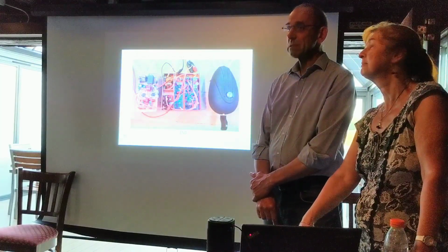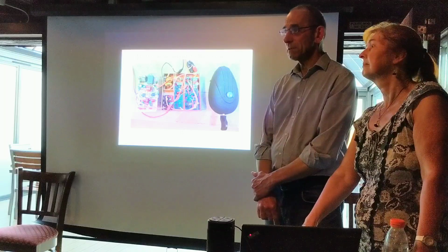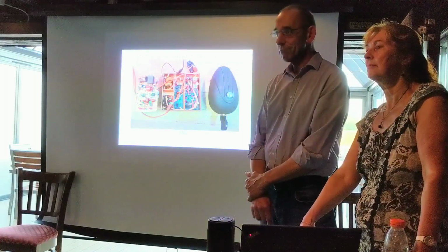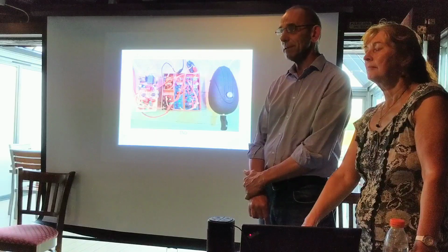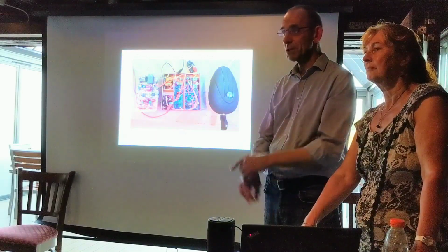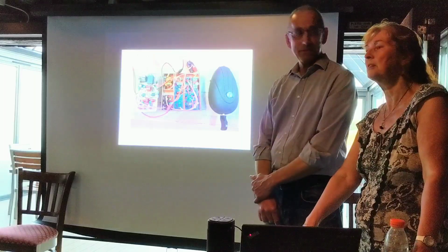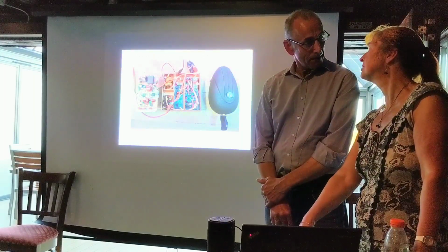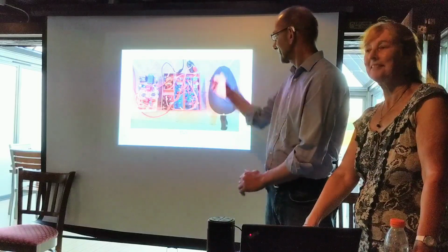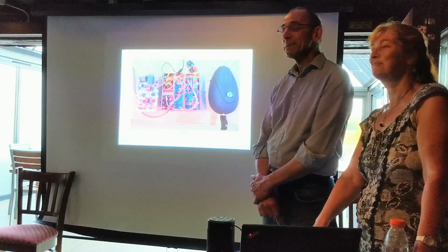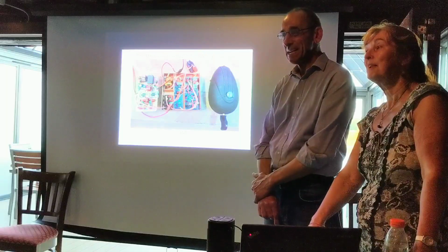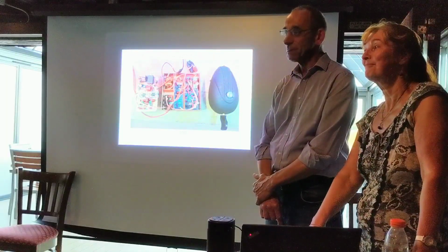But the one thing I will say is front end filter. It's that bandpass filter at the front end of the receiver. That's what really made the difference, spending some time getting rid of everything else apart from 17 kilohertz. And the sharper you can make that. Sorry? You said 472, it's 17. Sorry, 17. Yeah, brilliant. Really good. It was worth it, so persevere. But make a decent front end filter.